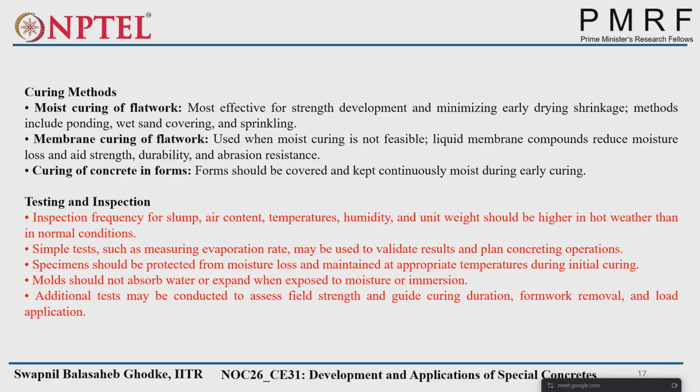Yeah. So what happens? Creep: a certain load comes in the initial phases. Because of that initial load, some deformation will happen, and deformation happens most importantly because of the cementitious contents, not because of the aggregate content. So in the initial phases, if concrete is not properly hydrated through the whole column, inner and outer also, there is a high chance of deformation.